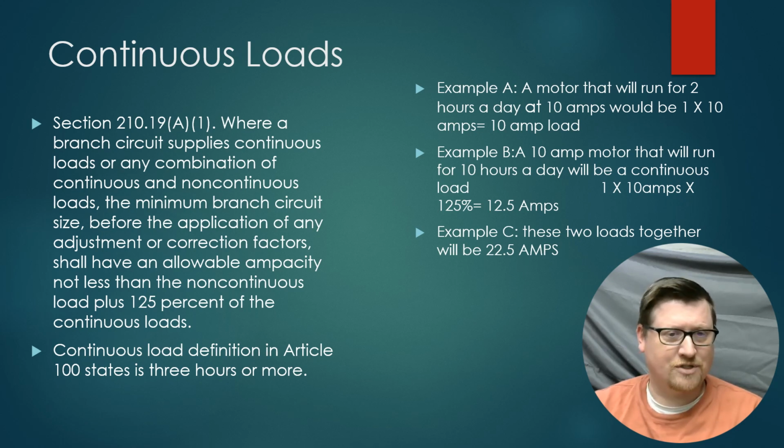Now it's like, if it's a 10 amp motor, it's only using 10 amps, right? But we're going to choose a wire that's good for 12.5 amps, so that it has better conductive qualities, so that we don't build up too much excess heat. So we've got an example here. Let's look at our example.